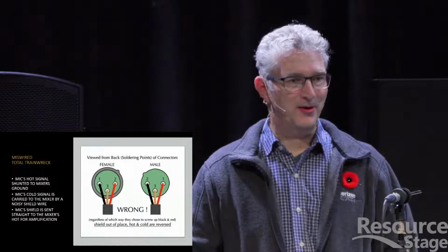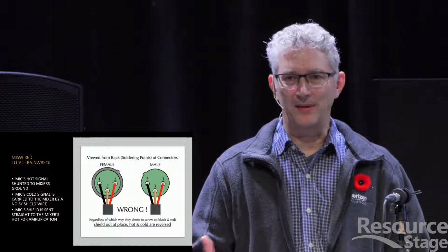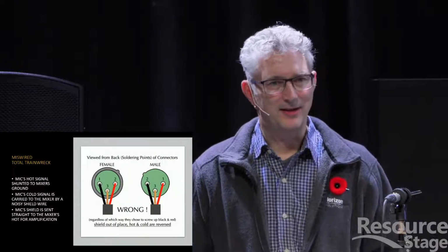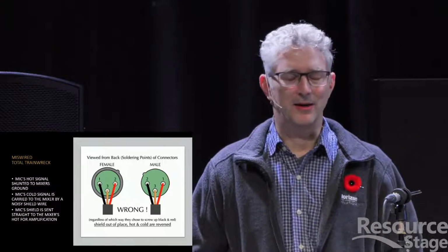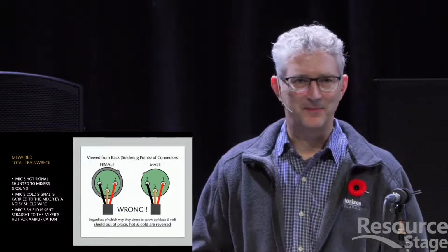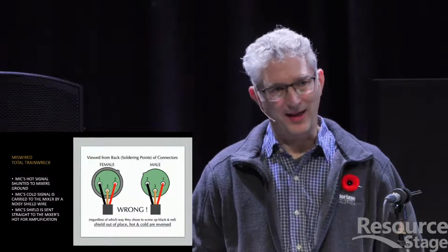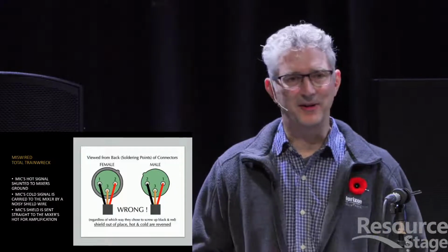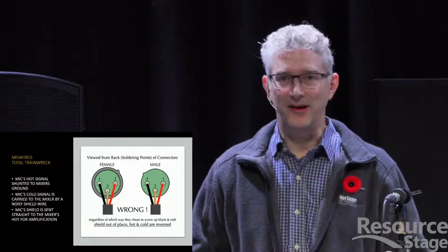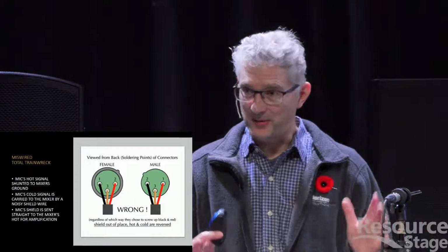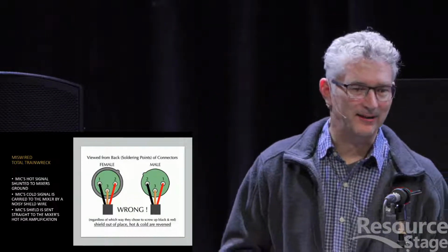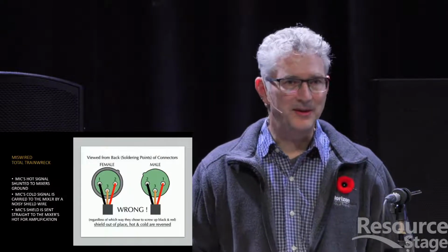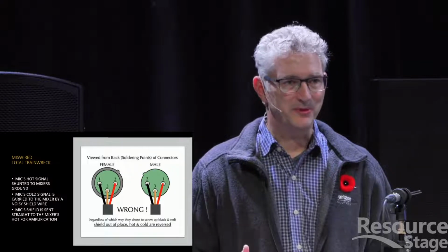He took the cable back to the store and said, this doesn't work. My condenser mic doesn't work with this cable. And the store owner said, well, you forgot to turn on the phantom power. And he's like, no, I tried that. I tried a different cable, and it worked. After doing a little bit of checking, they tested the cable, and they found it was wired incorrectly. I'm not sure how it was wired incorrectly, but it was. They gave him a new cable, and away he went, happy. So it's really, really important to test your cables.